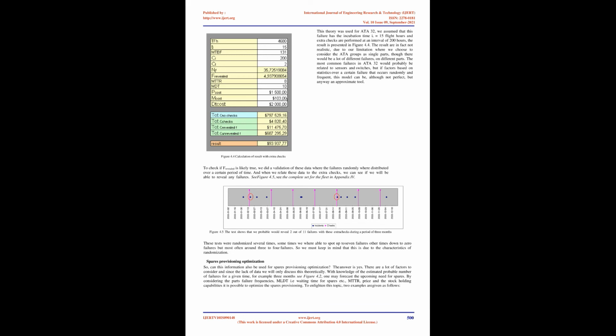4.48%. So, with knowledge of the total flight hours within the time frame TFH, the cost of the unscheduled maintenance, i.e. downtime DT cost, incubation time Ti, MTBF, how long the extra check would take CT, the interval of the extra check CI, MTTR to repair the failure, MDT, the maintenance cost per hour, and the cost of the part needed, we can calculate the approximate savings, or losses, that the extra check would gain. The total costs to repair the failures revealed due to these checks, here we assume that these repairs do not affect the operational availability, are then.